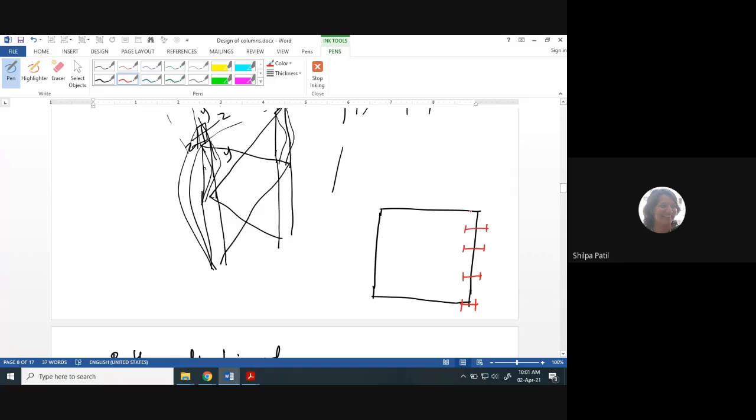Always. So that above the weaker axis we can provide the bracing system here, either in the interior side or the outer side of the building. We never place the column like this. Okay, this is the wrong practice. This is the correct practice. Okay, is it clear to everybody?